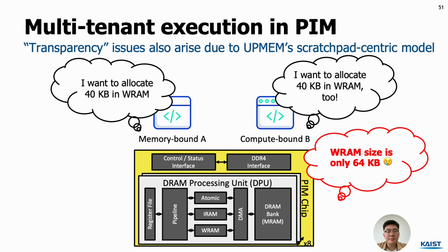However, even if UPMEM PIM does have an MMU, there is another significant problem that needs to be resolved. Since UPMEM PIM only supports scratchpads without a cache, when two PIM applications are to be collocated and they each require more scratchpad memory than the physical limit, the system will crash. Consequently, collocating both of these workloads requires a non-trivial amount of changes to both collocated PIM programs to make sure the aggregate scratchpad usage fits within the physical limit, arguably an unacceptable requirement to enforce on end-user application developers.